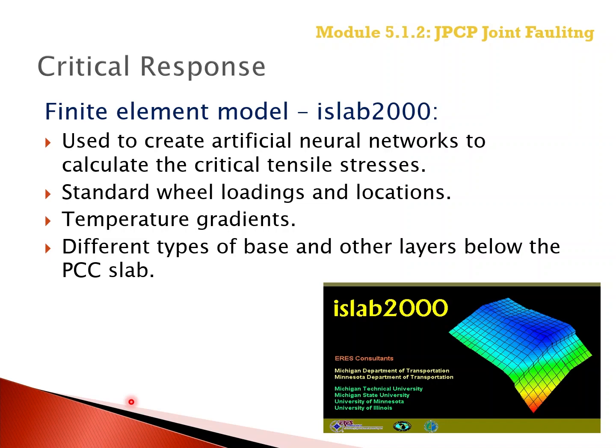Millions of runs were made with ISLAB 2000 to calculate critical rigid pavement responses, which were used to create the artificial neural networks embedded within Pavement ME design software. The artificial neural networks in the Pavement ME software are used to calculate the critical responses for predicting faulting of the jointed plane concrete pavements.